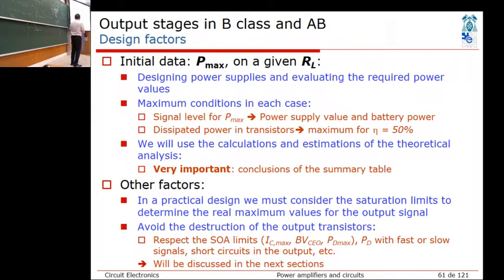Then of course the current, you need to take care of that it has enough of the current amplification beta. Yeah. If you don't have enough of power current amplification, you may end up having the worst case scenario by accident. So running with the highest design efficiency might actually end up being running it at lower current, meaning the higher power dissipation on transistor.